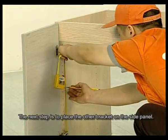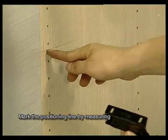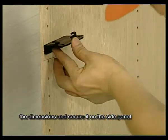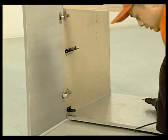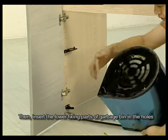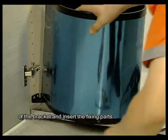The next step is to place the other bracket on the side panel. Mark the positioning line by measuring the dimensions and secure it on the side panel. Then insert the lower fixing parts of garbage bin in the holes of the bracket and insert the fixing parts.